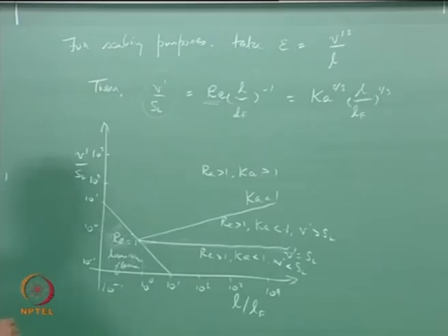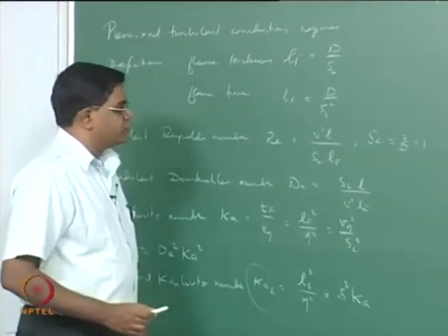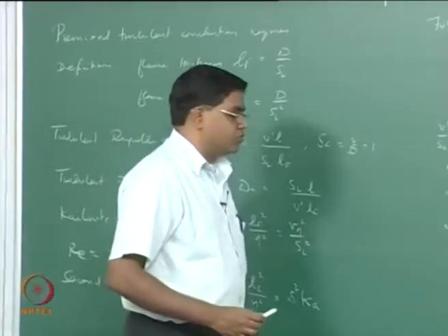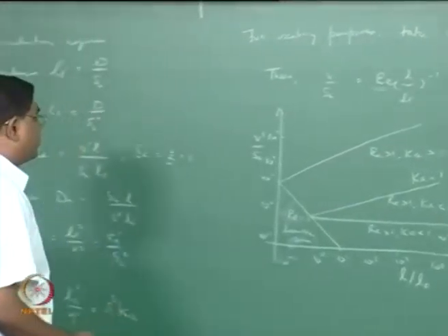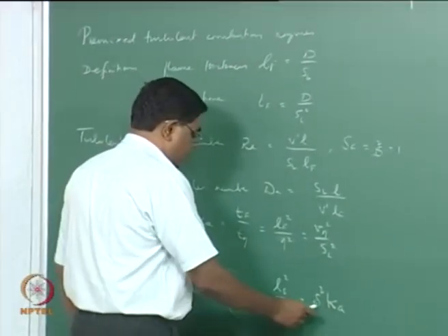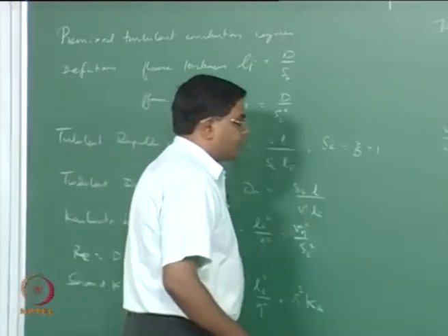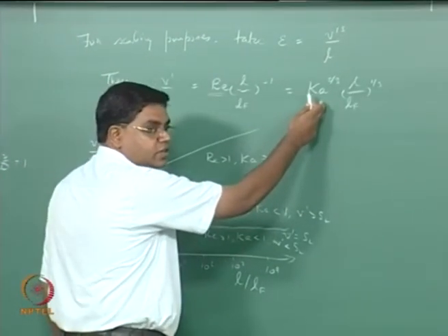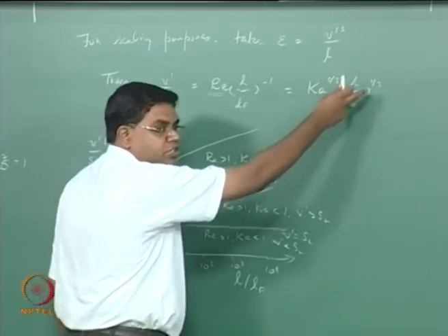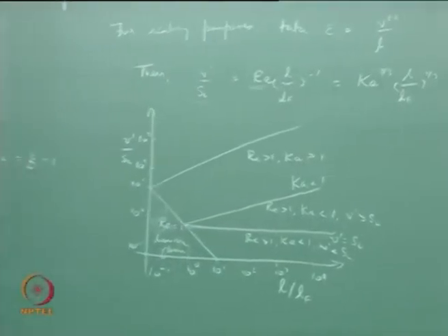right? And finally we want to look at the situation where the second Karlovitz number is greater than 1, right? So we now have a boundary, and that is also going to go the same way, because the Karlovitz number, this is basically delta squared times Karlovitz, so they are directly related. So V prime over SL in terms of Karlovitz delta, Ka delta, is also going to have a 1/3 relationship for L over LF, with simply a different coefficient, delta squared.